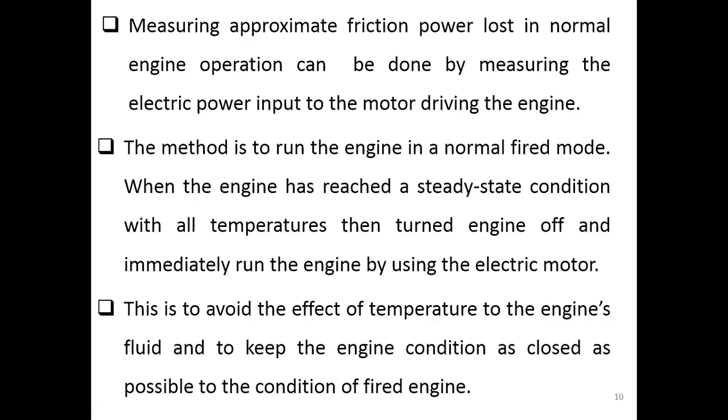So overall, we just want to keep the engine conditions as close as possible to the condition of normal engine operation. And then we measure the electric power that we supply to the electric motor, and the amount of electric power that we supply to the electric motor will represent the amount of the friction power.